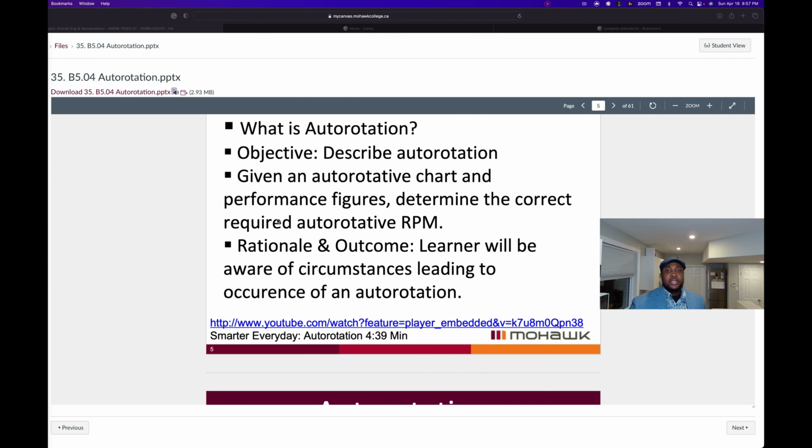So if we have a ball that's in a valley, if we disturb that ball, the tendency is the ball will eventually find its lowest point and return to stability. And this is known as positive static stability. If we have a ball that's on top of a hill and we disturb that ball, the ball is not likely to return back to its original position, and we name this negative static stability. In terms of dynamic stability,